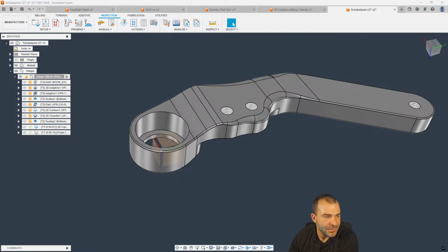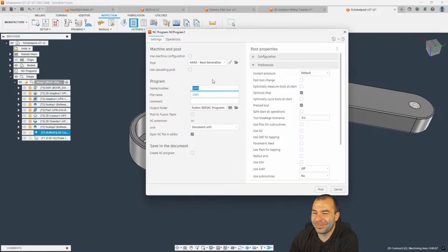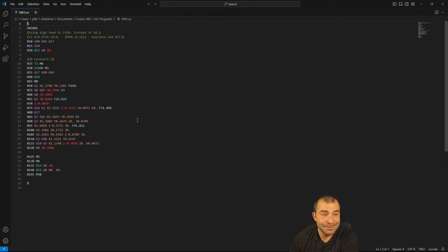Okay, yep. So you're going to manipulate the G code, or we would have to modify your post processor. When you do keyway broaching, I'm going to take any toolpath here. Normally, the trace toolpath, as per Matt Van Loo out there, works quite well. But upon posting, and it's going to be based on what your machine can do, you're going to remove this line of code, which is your spindle being turned on.